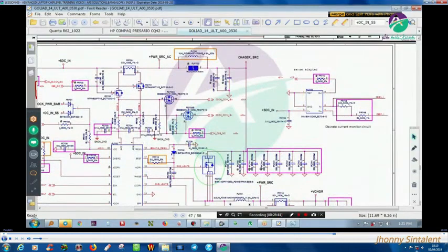See the difference here. Here it is written as power SRC AC. AC means 19 volts coming from the adapter. Here you are getting one more power SRC coming from the charger IC. That means you will have 13 volts. So these 13 volts will go to every section, the drain of the upper MOSFET.